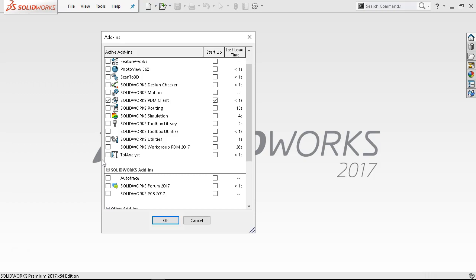I think my frustration with tolerance analysis is that I haven't done it enough to be fast at it, and most of the time I can look at those parts and do the math in my head faster than I can set up. So I usually end up just sitting down and scribbling out, okay, worst case scenario, I'm going to have 2 thousandths of clearance or 2 thousandths of interference or whatever it is that I'm analyzing for those parts. But we'll take another stab at it.